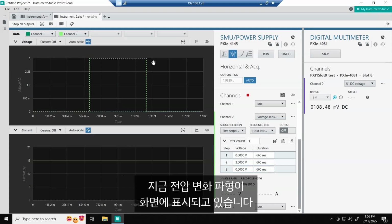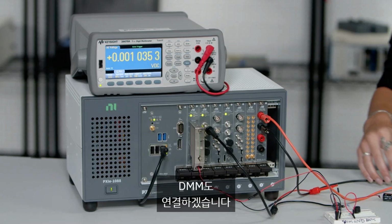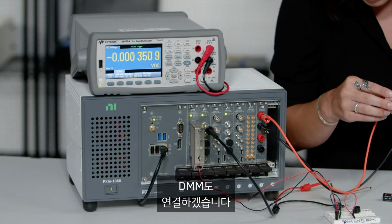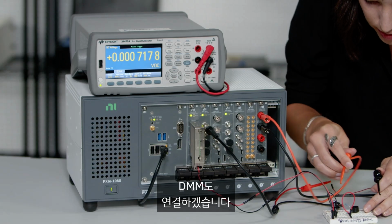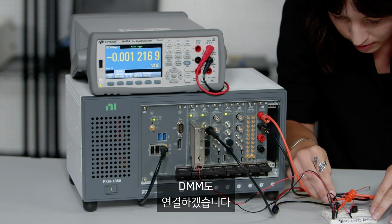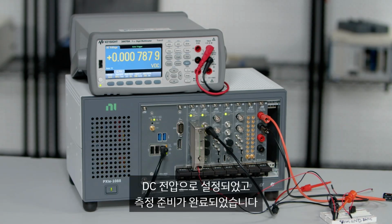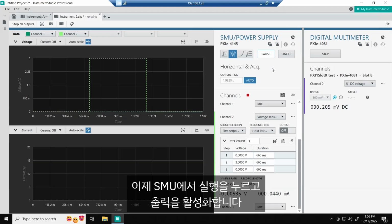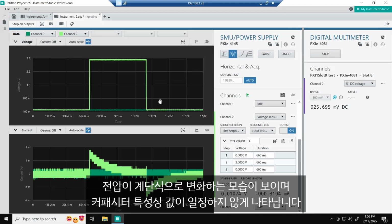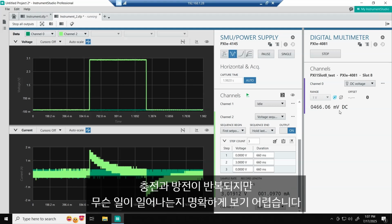All right, so you'll see we've got our waveform here. I'm going to connect my DMM as well, and that's going to be on this side. All right, so I've got this set to DC voltage, so we're all good there. I'll press run on my SMU and turn the output on. And so you'll see that we've got our voltage step here, and we're measuring our voltage, but it's kind of all over the place, as we would expect from a capacitor. It's charging and discharging, but it's hard to really tell what's going on there.